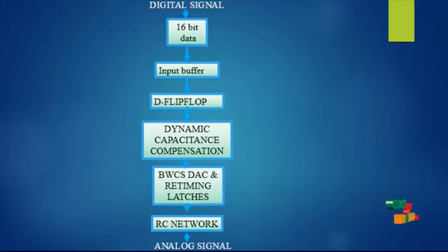The flip-flop is important for clocked flip-flops as it ensures that inputs S and R are never equal to 1 at the same time. The D-type flip-flop is constructed from a gated SR flip-flop with an inverter added between the S and R inputs to allow for a single D input.